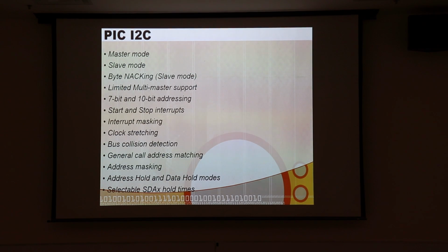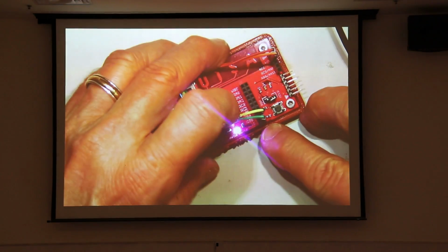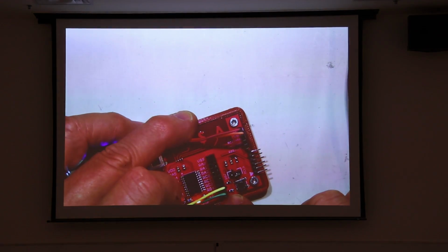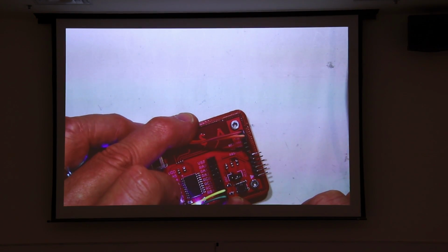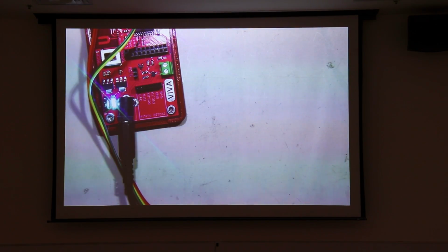The lines are pulled high with resistors, and if you look on your board, we did put the pull-up resistors on. They're right down here. You can see the two little resistors right above my finger, right next to RB6 and RB4. I used 3.9 K ohm resistors for them, kind of a mid-range. You can run anywhere from 2 K or 2.5 K to maybe 5 K, depending on how many peripherals you have hooked up. So we went ahead and put on these pull-ups.